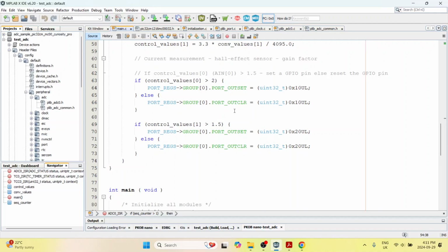Choose different values and see for yourself how the pulse changes and verify that you can accurately pick out precise locations of your sawtooth waveform, which would give you confidence that you have precisely captured your analog signal. And now if you write any control code, you are using precise values with which you can control your circuits to a fair good amount of accuracy.